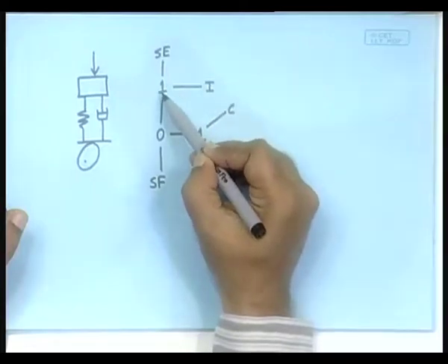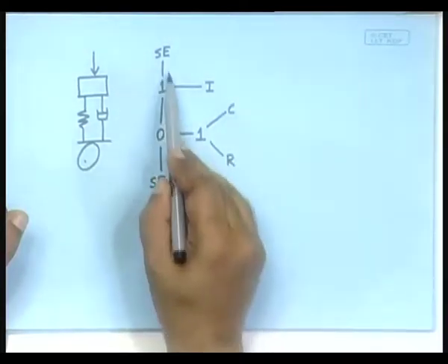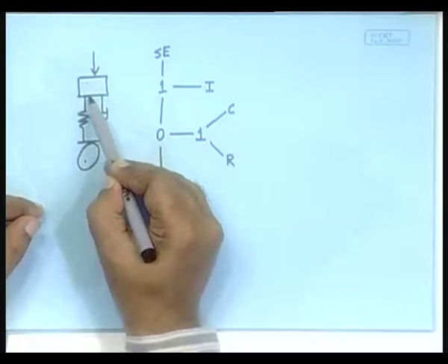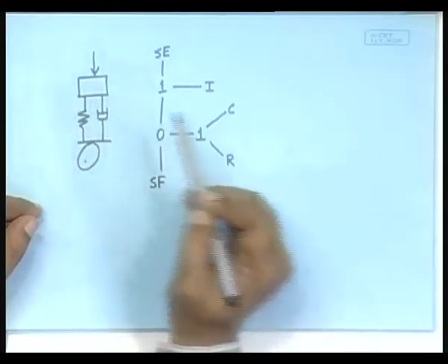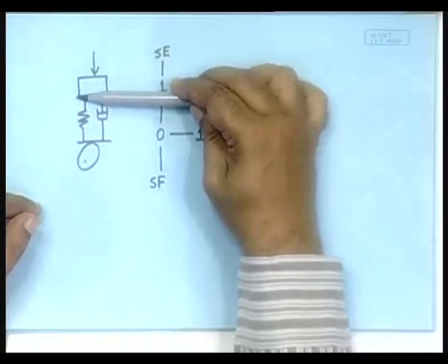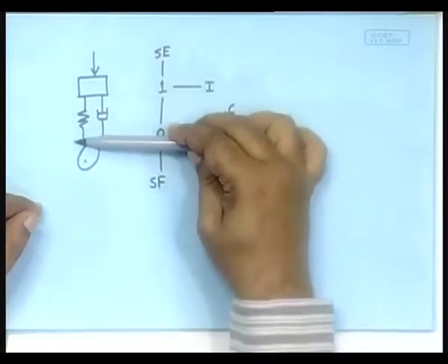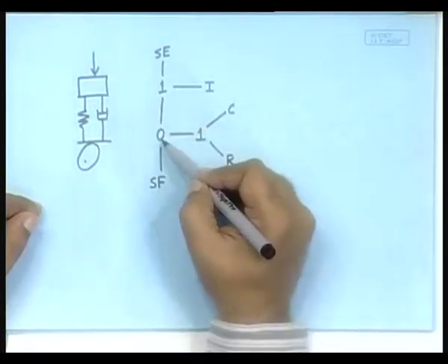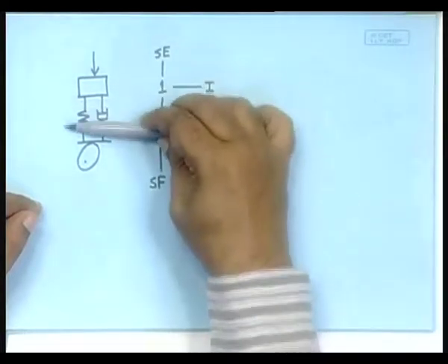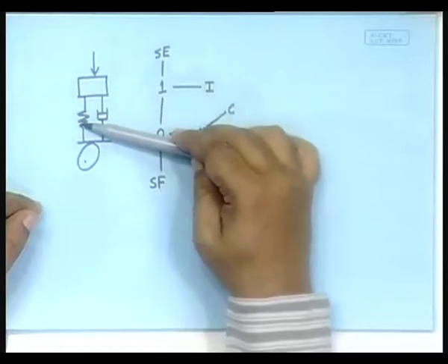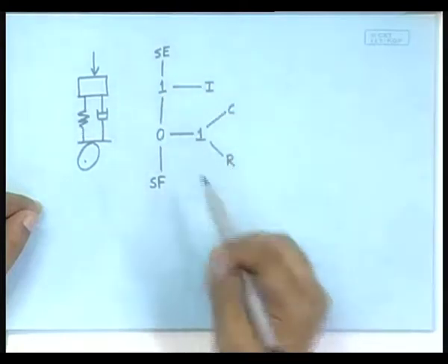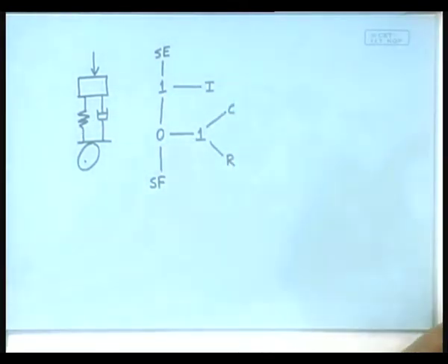Notice the logic: here is a 1 junction, and that 1 junction is distributing the same flow to all the sides, and that is exactly what is happening. What is sharing the same flow? This AC element, the M, and these two ends. Whatever is at this end and the whole end share the same effort, and that is why we have connected the top and the bottom through a 0 junction. And then we worry about what is in between. What is between this friction element and the compliance element share the same flow; they have to move together. So, they are connected by a 1 junction. So, that was the logic.